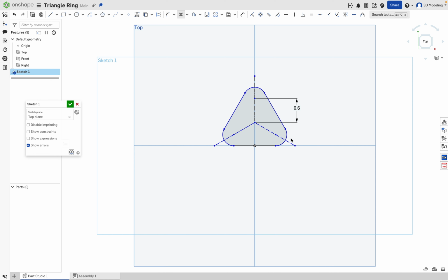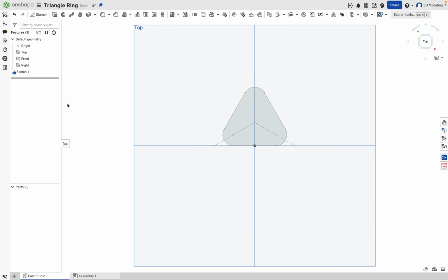right here if we left it like this in other CAD drawing programs. But here, even though we remove this outside geometry, we are still good, because Onshape allows us to leave the sketch as it is with all of the geometries locked in when we delete them. Other programs will show you an error and show you there are multiple degrees of freedom, meaning that you can move this around. So let's go back and click OK.